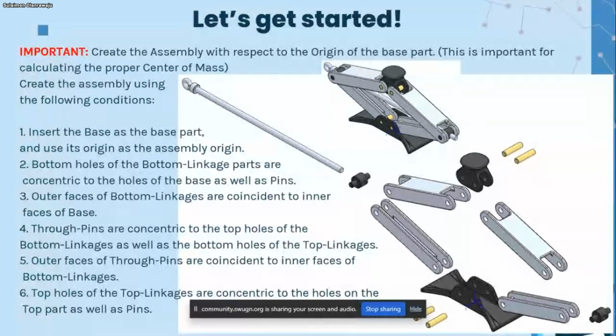Now, one thing about SolidWorks I like is that if you notice their assembly mates, the names are also kind of the same as in your sketch environment. In your sketch environment, you have coincident, parallel, concentric, tangential, and so on and so forth. So these names, you meet them also in your assembly environment.